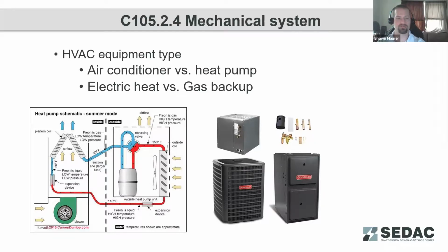And that they're also not going to be having issues with that reversing valve or a situation where you might have simultaneous heating and cooling with those backup systems when the system is in cooling mode. So just making sure that the sequence of operations is correct on those heat pump units, that backup emergency heating is only going to be operating when it's needed, and that reversing valve is working properly.